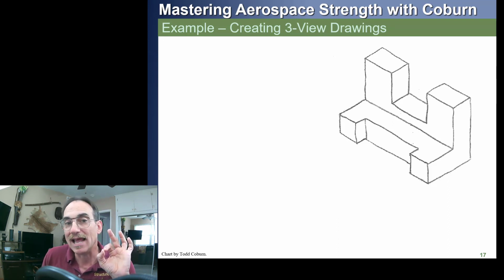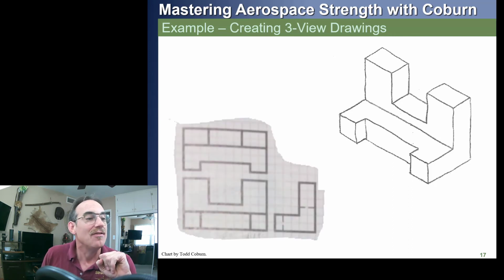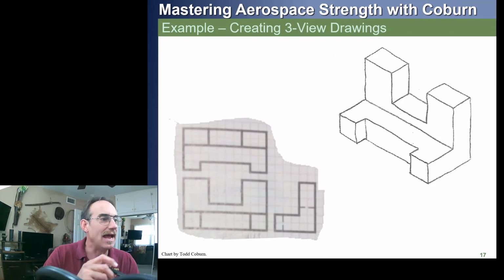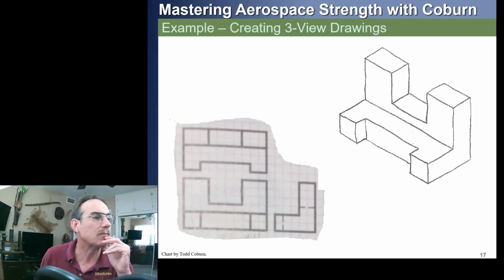Once again, what can really help is if you just have quad paper. If we had quad paper, then those quads can help us. You can see we first draw our front view, we draw our leader lines going up for each feature, and then transfer our features from the one view to the other. So we see, if we draw this view to scale, then we extend our leader line up.